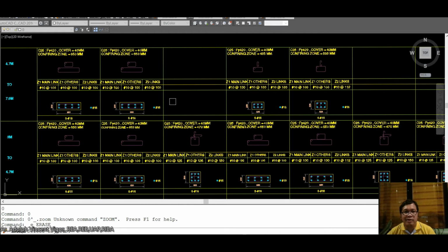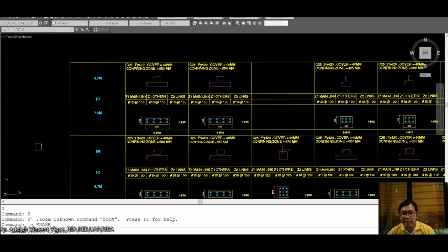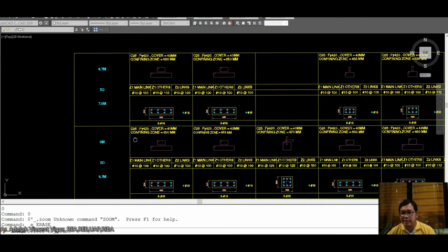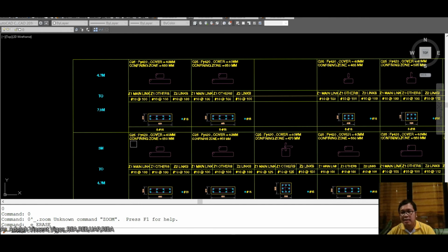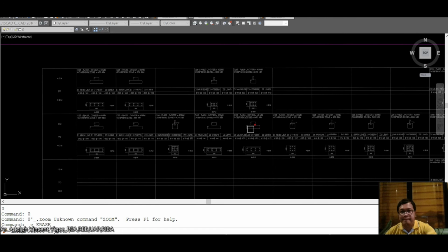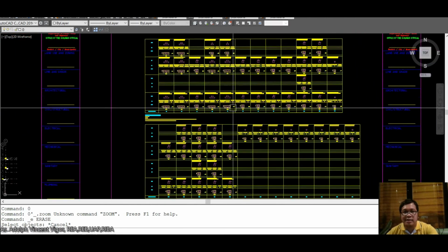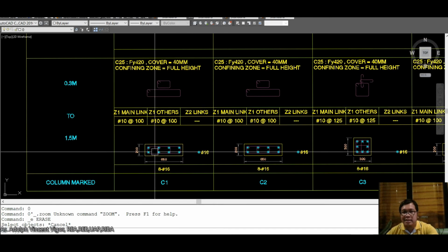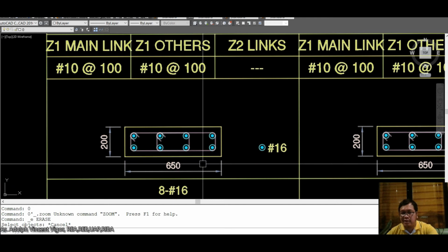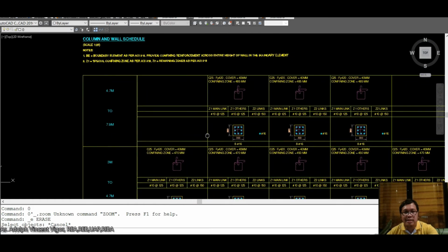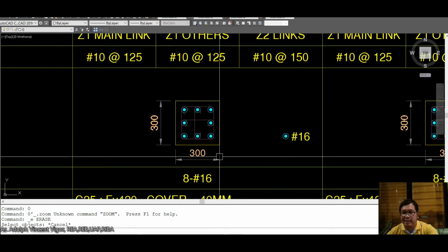So this is an example of another way to do it. If the structural design of the structural engineer is somewhat different at different lengths, this is one way to present them. This is done in AutoCAD. So you can write from point 3 to 1.5 that this is the drawing. This is how the reinforcements are going to be arranged.